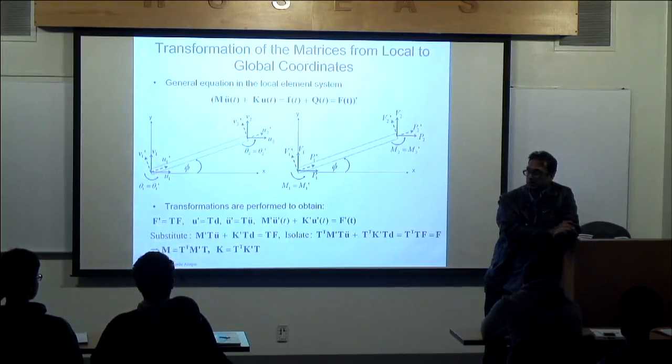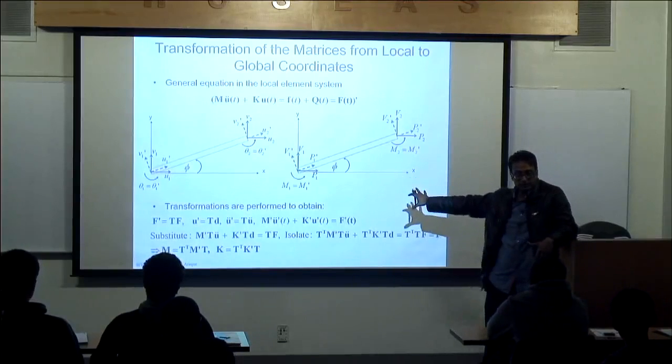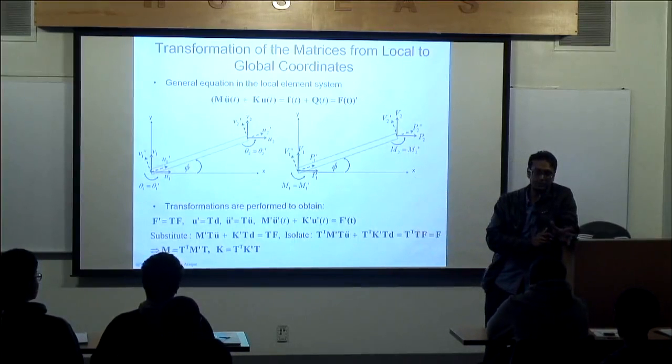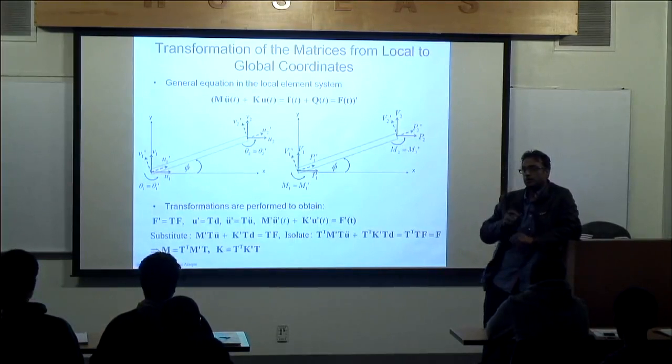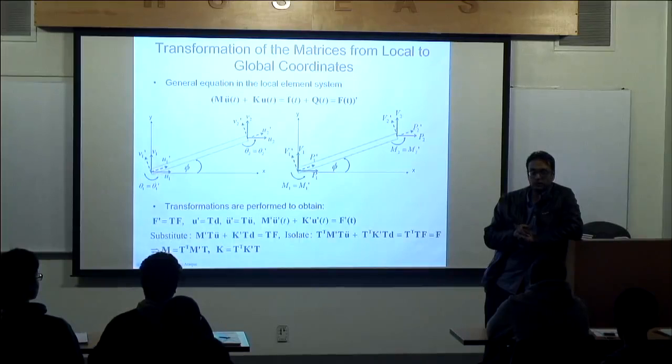So what we learned is that in a transient problem, we're discretizing the spatial domain using finite elements, and then we're integrating the equations of motion over time using the Newmark beta method. In the heat transfer problems, we can just use the forward, the backward, or the central difference method. And so, with that said, I think we're ready to now cover dynamics next Thursday for a special class of problems where we'll talk about modal dynamics.